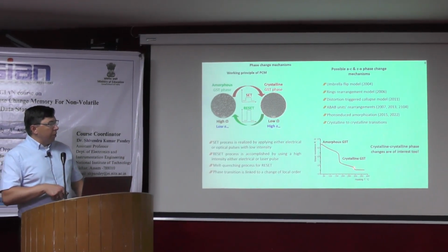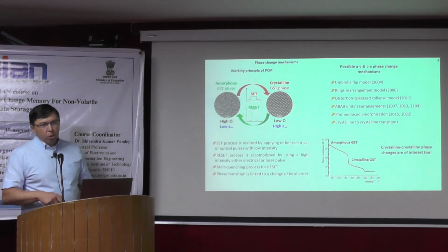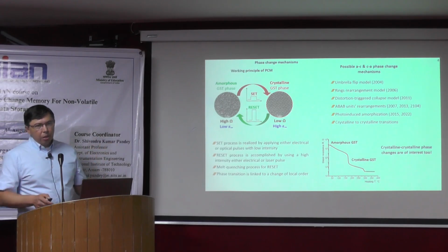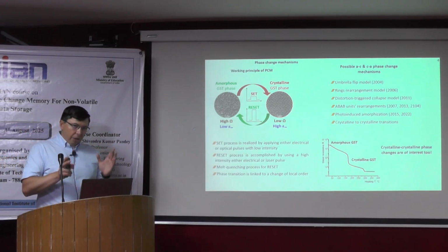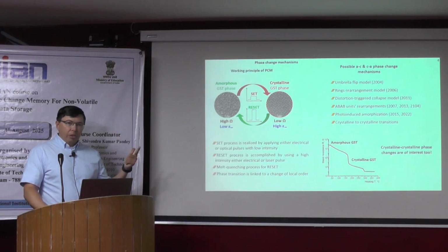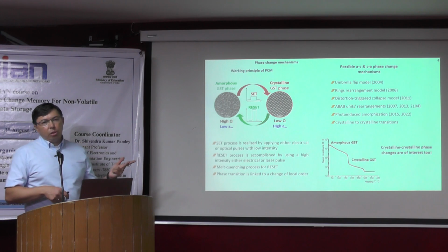It can be a little bit extended, but the problem here, which I did not discuss, is that at some temperatures you have a mixture of the vacancy ordered and the trigonal phase. After 220 we observe the formation of both phases mixed. But for vacancy order there is a window. You have to identify it for your system, because it's compositional dependent and also thickness dependent. And it's also heating rate dependent, how fast you heat your system.